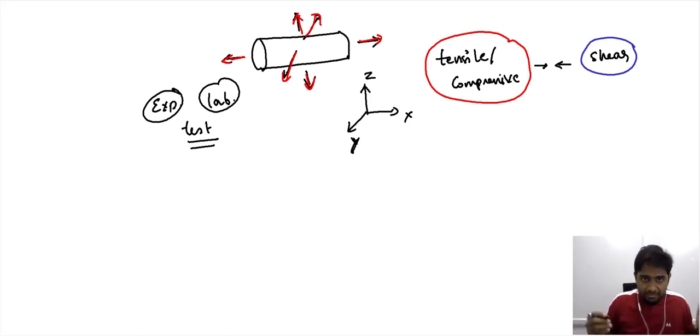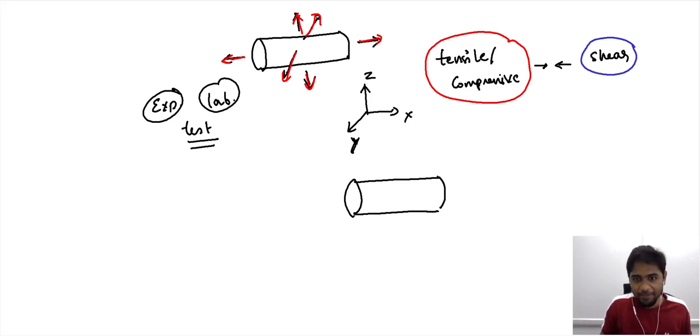Now let us begin, instead of starting with the triaxial tensile loading, with a simple uniaxial tensile loading. When you consider a sample such as this, of course, it is very rarely we find a sample of this form in a real life application. Nevertheless, our focus is now on the mechanical condition. So in an experimental setting, the uniaxial loading condition will be of this form. Now when you consider an equivalent real life case, it is not necessary that the loading direction is along the x-axis. It can be inclined. So it can be inclined in this manner.